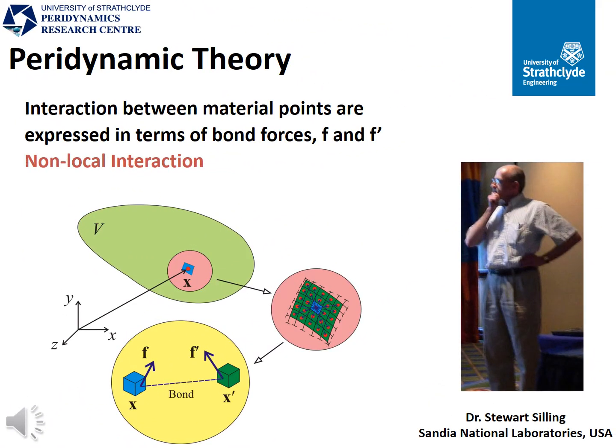As I said, peridynamics is a non-local continuum formulation, and according to continuum formulation, a body is composed of material points. In peridynamics, a material point not only interacts with material points in its neighborhood, it also interacts with all the material points through peridynamic forces.